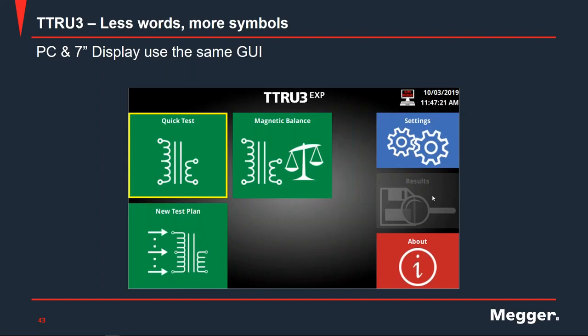Okay, if I may add one point, because it's important to mention that the 30-degree phase shift you're talking about, DYN1, represents a phase shift between a line-to-line voltage on the primary side and the line-to-line voltage on the secondary side. That 30-degree phase shift comes from one side being delta, the other being Y. And if you talk about YN0, there's a 0-degree phase shift.